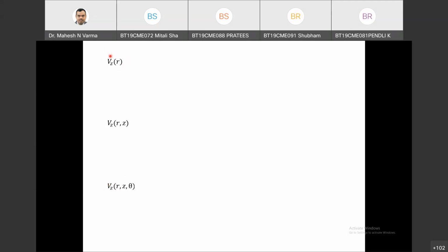Now this we have seen. We have solved almost three problems. So how can it be solved? This can be solved by using two boundary conditions. These two boundary conditions are needed because I have a one-dimensional second order differential equation. These two boundary conditions can be one flux condition and one velocity condition, or two velocity conditions. This we also saw in the last problem, where we solved flow through an annulus in a concentric pipe. With two velocity conditions we can get the velocity profile equation.